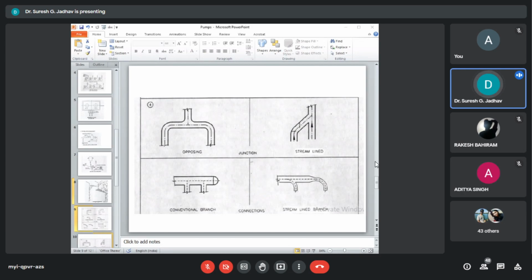Auxiliary manifolds supply cooling water, seal flushing fluid, and gland oil for pump circuits. Heating or cooling shall be located overhead and nearer to the pumps.